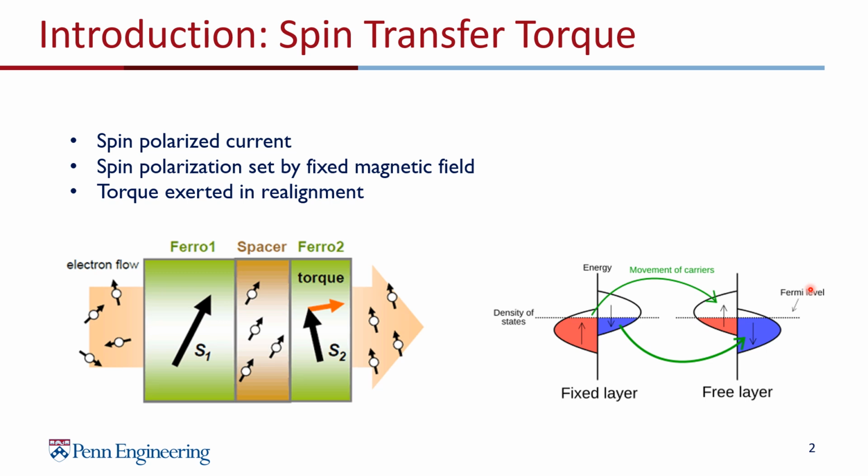The ferromagnetic materials are able to retain magnetic polarization when subjected to a strong enough magnetic field. In the magnetic tunnel junction, one of the layers, here on the left, is a permanent magnet with a fixed spin orientation, and the other one is free, meaning its orientation can be realigned. In the middle, a thin isolating barrier allows for tunneling magnetoresistance, which modulates the resistance of the magnetic tunnel junction depending on the state of the two ferromagnetics.